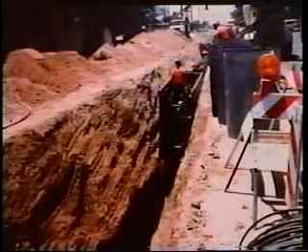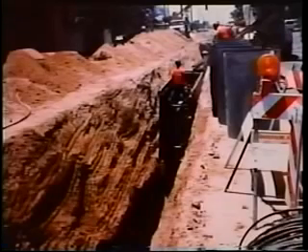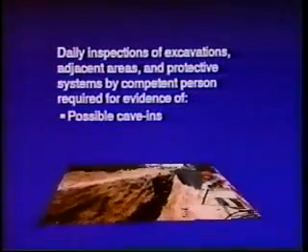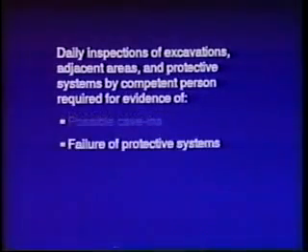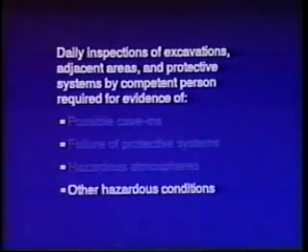Protection of employees from materials or equipment which could fall or roll into an excavation shall be provided by keeping them at least 2 feet from the edge of excavations, or by the use of adequate retaining devices, or by a combination of both if necessary. Daily inspections of excavations, the adjacent areas and protective systems must be made by a competent person for evidence of a situation that could result in possible cave-ins, failure of protective systems, hazardous atmospheres, or other hazardous conditions.